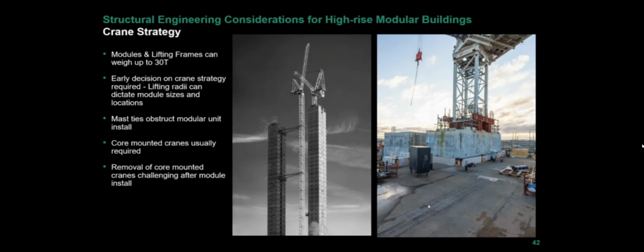So in a traditional high-rise building, as you see around London, once you go above, say, 25 stories, you generally need to tie in your crane to the building. So to build the cores, we would put in an external crane, which is tied to the core in a traditional manner, which would build both cores, which you can see in the middle photograph there.